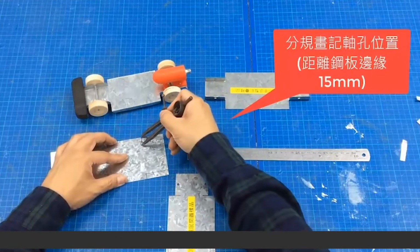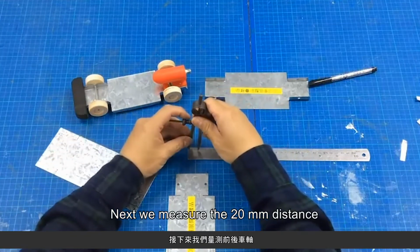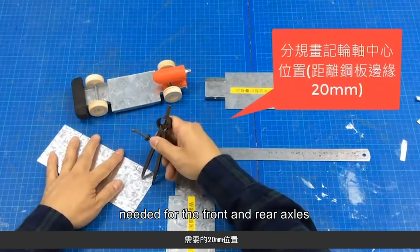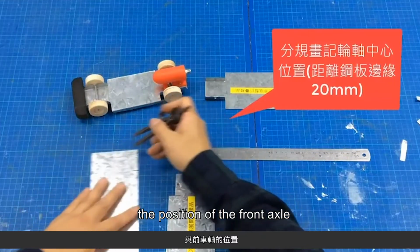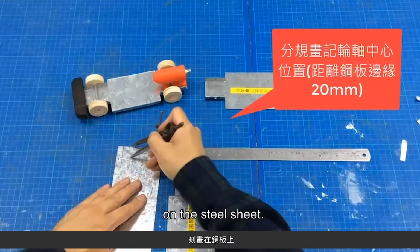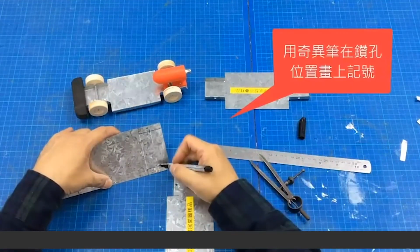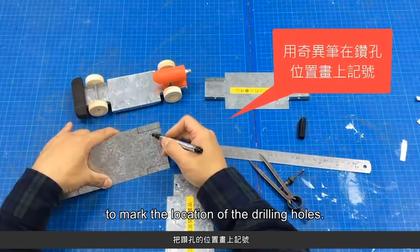Next, we measure the 20mm distance needed for the front and rear axles and mark the position of the rear axle and the position of the front axle on the steel sheet. We also use a marker to mark the location of the drilling holes.